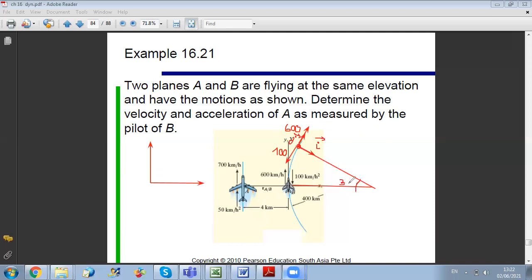Okay. Now here you can select any frame to work with. You can move easily from small i, small j to big I, big J. So for example, if you want to calculate the V relative, okay? What was the expression of V relative? V relative is equal to VA minus VB minus omega vectorial BA. Okay? Now, what will be different here?